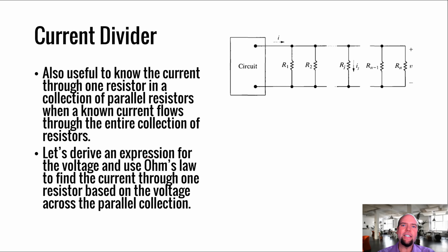We're going to basically analyze this the exact same way we did the voltage divider equation. And you'll find that the solution for these, anytime we have a current equivalent of voltage, parallel equivalent of series, the analysis is always going to be very complementary. So basically, rather than a KVL, we do a KCL. Rather than doing a parallel collection, we'll do a series collection. We're always going to use the complement to find the solution. So if you know the solution for the series version, try to think about the complementary approach to finding the answer for the parallel one.